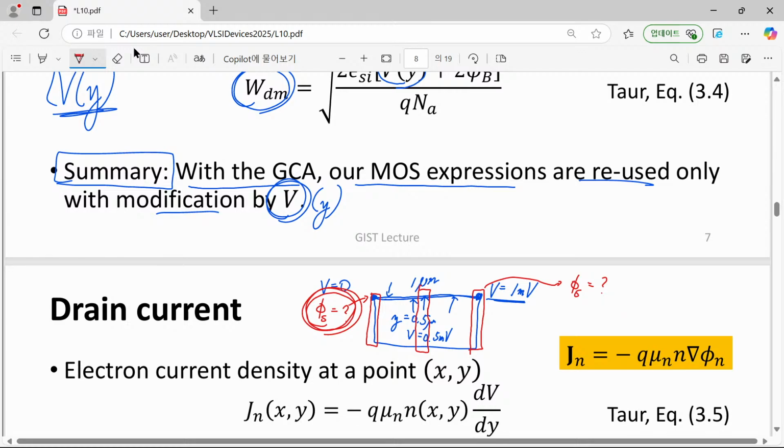So in general, although we have to solve the 2D Poisson equation, by understanding and adopting these approximations, now we were able to get a set of 1D equations. We have tons of equations. How many equations are there? It depends. If you introduce 100 slabs in your discretization, then you will have 100. Analytically, you will have an infinite number of slabs.